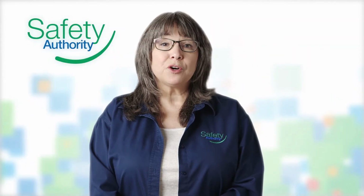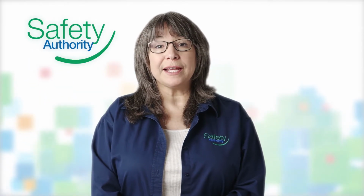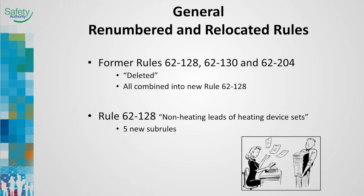Rule 62-118 was formerly 62-116. Subrule 1 has not changed. Subrule 2 is new. This subrule applies to service or feeder conductors supplying only heating loads. The ampacity of the service or feeder conductors may be sized and based on the maximum connected heating load supplied at any one time. Some rules have been deleted and combined into the new Rule 62-128.